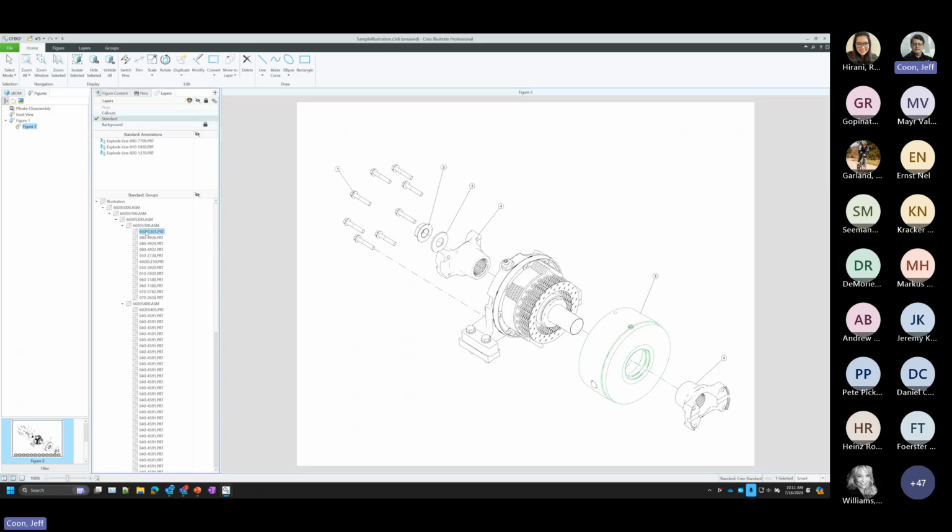Again, you can come in here and right click on things. You can create groups. You can rename the group. You can create duplicates that are either linked or unlinked. Basically, if you duplicate a group that has a link back to the 3D CAD, it'll still have that link. So if the CAD updates, so too will this the next time you refresh it.